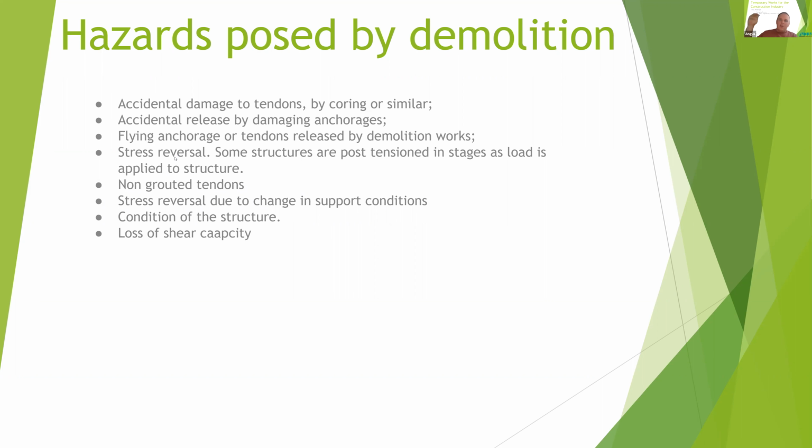So if you then start demolishing that building from the top to the bottom, you need to take that into account and release the compressive force that's been locked in through the tendons. Otherwise, you can break the back and reverse the stress in the beam itself. Quite a specialist area, not something to really go into here, but it's something to think of nonetheless. It doesn't behave just the same as a reinforced concrete slab at all.